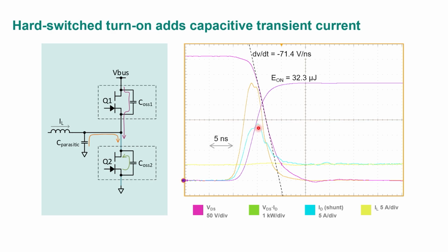So think about that. If my transistor limit is 40 amps and my inductor current is 30 amps, and I switch on quickly in hard switching, what is the peak current at that moment? Well, it's going to be 30 plus this 20, so 50 amps. It could easily exceed the device current limit. Now, really short transients like this are usually squashed.